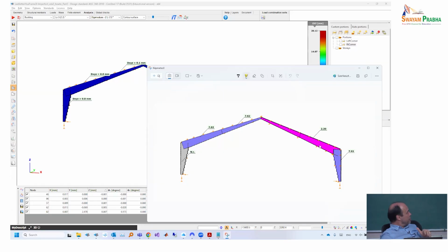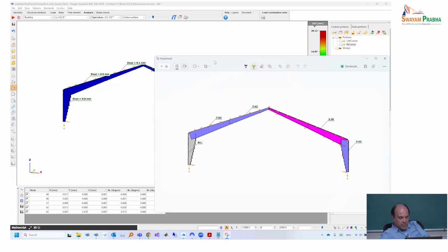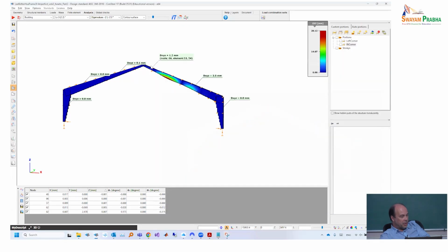So if you are really willing to go into this, it's always better to just select that one combination that is relevant and limit this game to that. Now here the results are more understandable. They all refer to load combination 3, which might not be the relevant combination for every member design. But if we limit our game now to load combination 3, then for the whole rafter, regardless of the fact that I made it from 2 members, 2.2 was recommended, which is this mode.